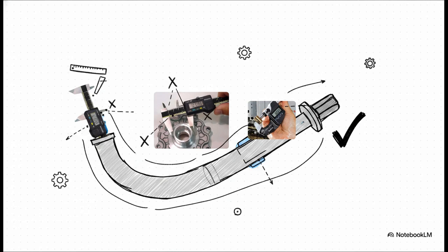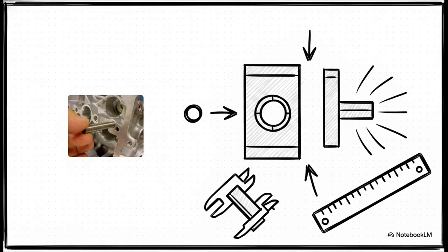This is exactly why just taking a few micrometer readings is never enough to guarantee a part actually conforms to rule number 1. So how do we verify that a part actually respects the rule number 1 envelope? Well, inspectors rely heavily on functional go-no-go gauges, like the functional gauge shown here, checking an internal boundary. A go gauge physically replicates the absolute worst-case mating condition, that virtual condition we did the math for earlier. If the part can smoothly slide into the go gauge, it completely proves that neither the size nor the form error has violated the maximum allowable envelope. It's a remarkably quick, physical pass-fail test that perfectly aligns with the real-world functional requirements of the assembly.